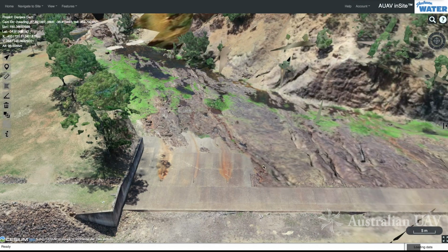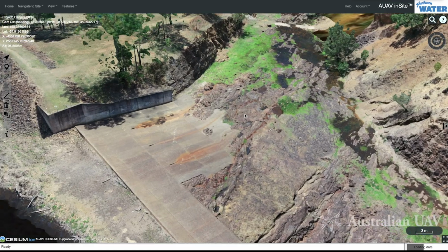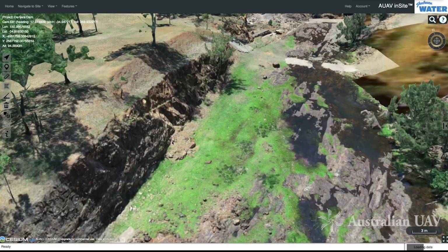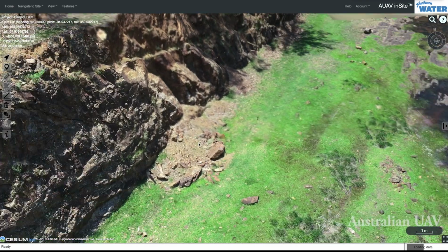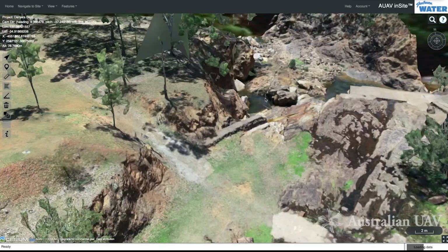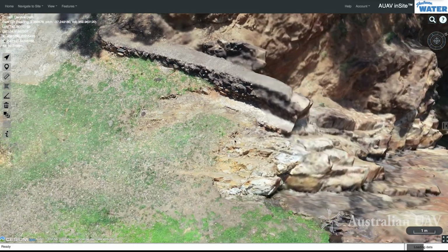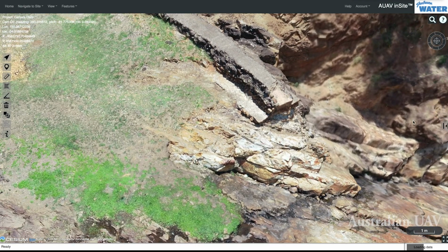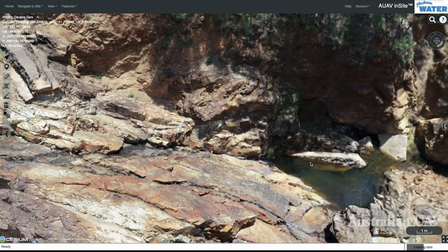Coming over to the spillway section, all the concrete at the top seems to be in pretty good shape. Looking a bit further downstream, we start to see this evidence of the erosion that was mentioned. A small breakaway section there, and what looks like a concrete remediation effort for the erosion, which has broken away, and you can find that a little bit downstream there.